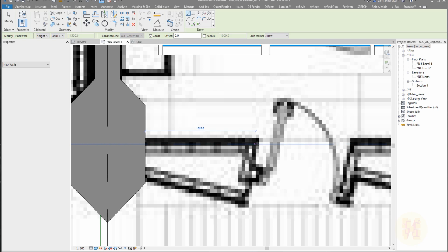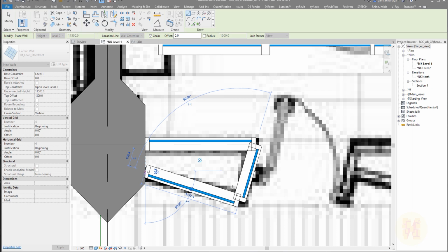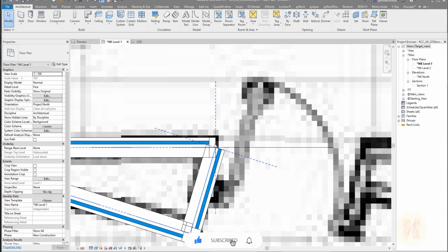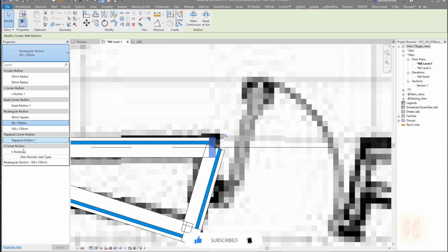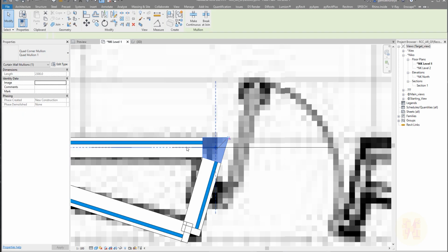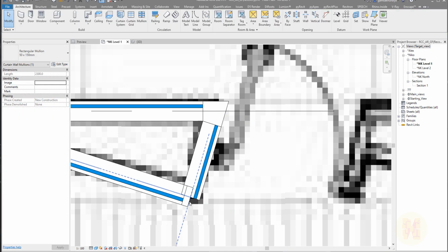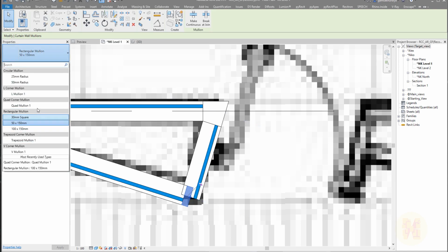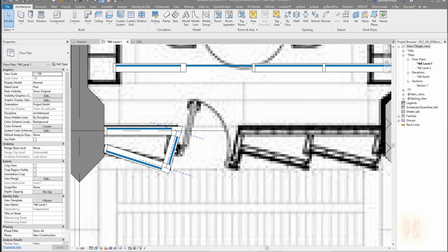So we can do it like this. Create one panel, another panel, and here the panel. And here, just delete one of the mullions, select another mullion, unpin it, and use the quad one. Now it's much better, right? Let me unpin it and delete, and unpin it and quad one. Now we can say this is what we want, but it's not finished yet.